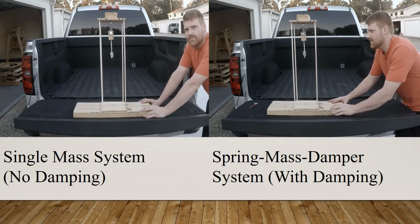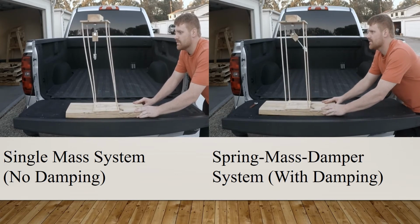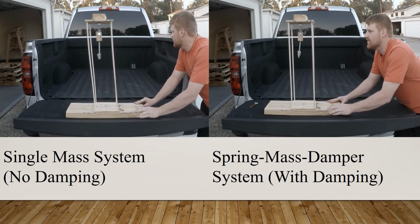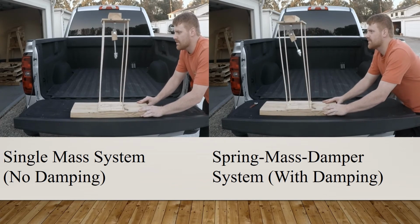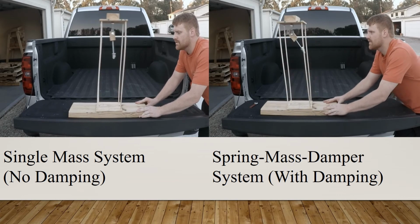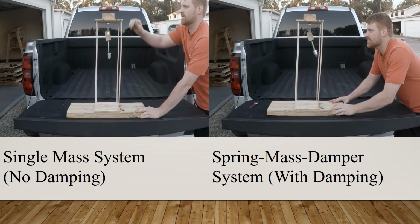On the left side of the screen, we have tightened the bolts connecting the damper to the skyscraper model so that it acts as a single mass system with no damping. This prevents the damper from having any relative motion to the model. On the right side, we have loosened the bolts connecting the damper so that it may absorb some of the mechanical vibration the system experiences. The damper will then help reduce the maximum amplitudes that the system experiences.